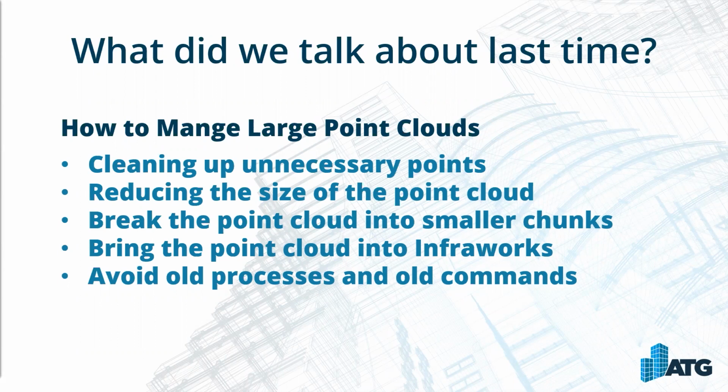Last time, we cleaned up a point cloud, so we went through a full workflow from drone capture, and then we went into Esri Site Scan, did some measurements. We exported that point cloud, brought it through Recap, and then brought that into Civil 3D, and also into InfraWorks to compare the surfaces. We highlighted that the tools built within InfraWorks really helped get a lot more detail with a smaller file size.